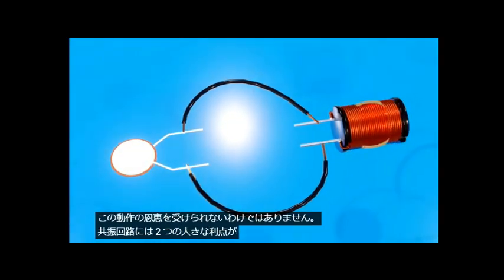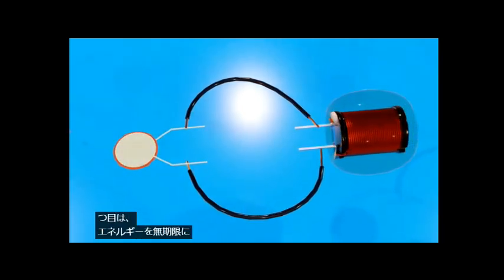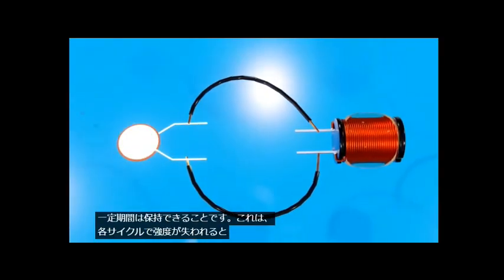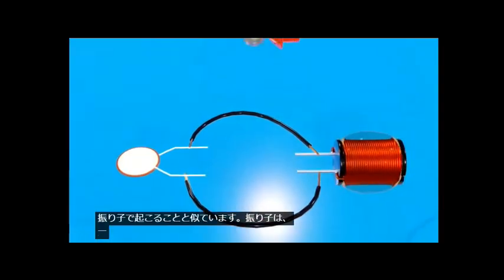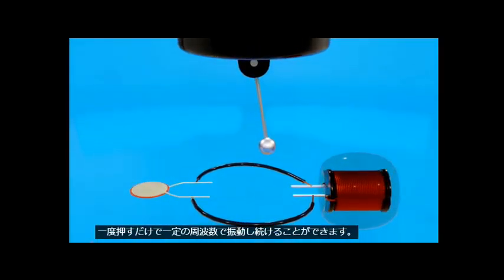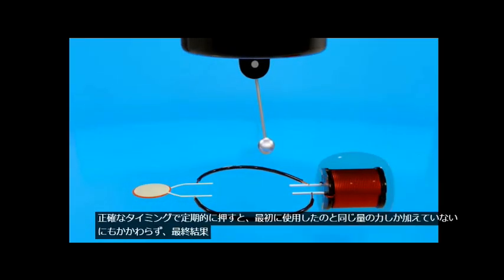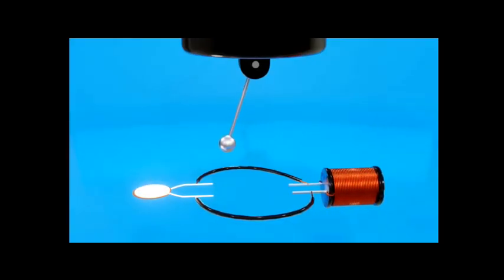A resonant circuit has two great benefits. The first one is that even when they can't hold energy indefinitely, they can do it for a certain period of time, although losing strength in each cycle, something similar to what would happen in a pendulum, which just by pushing it once, is able to keep oscillating at a regular frequency. And also, like a pendulum, if we push it periodically at the exact moment, we can amplify the end result, even though we are only applying the same amount of force that we had initially used.